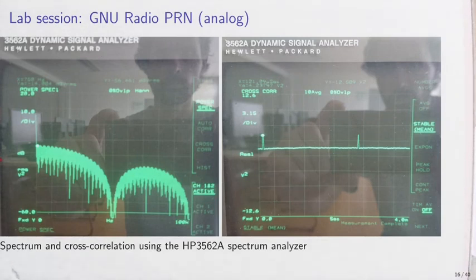In this example here, you see the flat spectrum of each individual PRN generator. Actually, it's a flat spectrum with discrete time sampling, because we are clocking. If you remember, in this example, we were clocking the linear feedback shift register at 21 kilohertz. So the notch here, this is the cardinal sine function, sinc function, which is due to the discrete clocking of the system, but this is a flat spectrum for each individual pseudorandom sequence generator. So this proves the flat spectrum, that it is indeed pseudorandom.